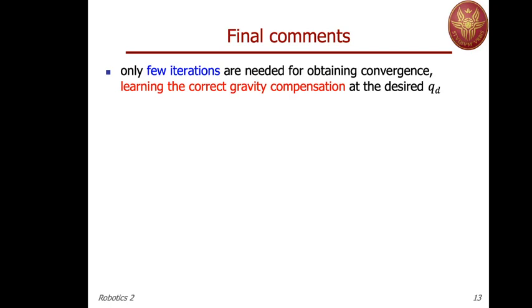Of course, if we have a new task, a new desired QD, then what we have learned so far is more or less of little use. So we could start with U0 being the learned term for the current configuration, which is the end of the previous task, but from there on we have to learn again online what is needed.